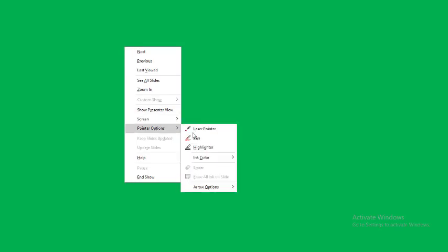So I hope all of us have the basic idea of what an LTI system is. So let us brush up that concept first. Consider this as an LTI system. The LTI system has an impulse response, say h of n, and it has an input x of n and output y of n. So the output y of n is related as x of n linear convolution h of n.